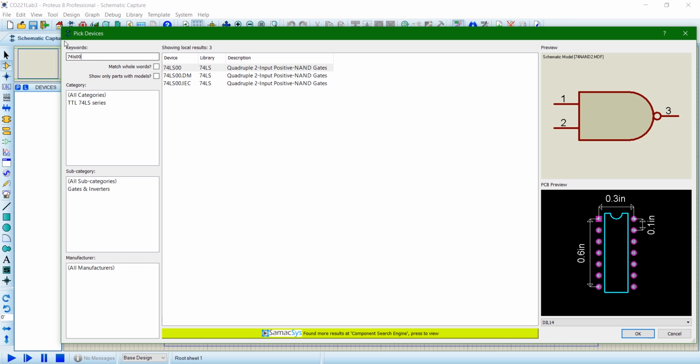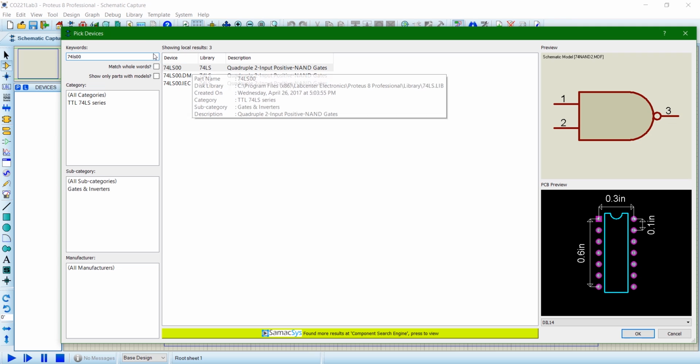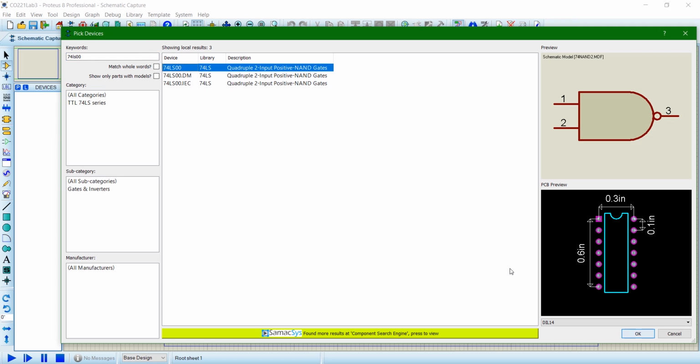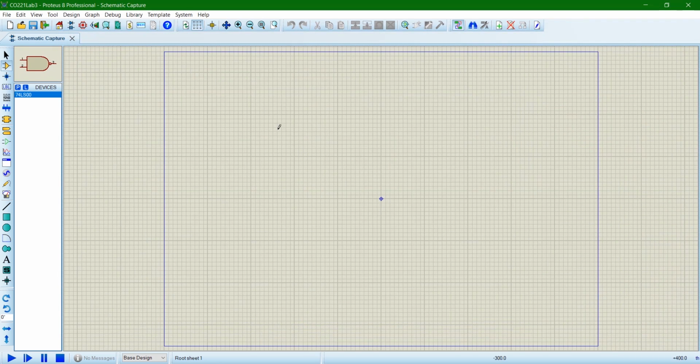Since we have been using the LS logic family when we were building circuits in lab, we'll be going ahead with the 74LS series. So choose ICs from the 74LS series when you are creating your circuits in these labs. So 74LS00, we'll choose it. So that's a NAND gate.